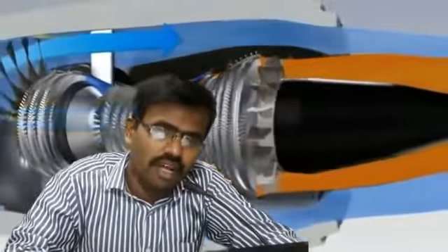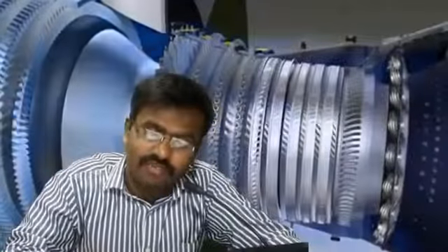Okay, so now we will recall this picture. The first step is a diffuser, second is the compressor, third is the combustion chamber, then the turbine, then the nozzle. These are the parts and the flow process of turbojet engines. See, in this picture we have the compressor. This compressor is driven by the turbine itself. This is the principle of working of turbojet engines. Right, this is a 3D picture of a turbojet engine. First we have a fan, and next the compressor and combustion chamber. See this 3D picture, it is similar to this 2D.